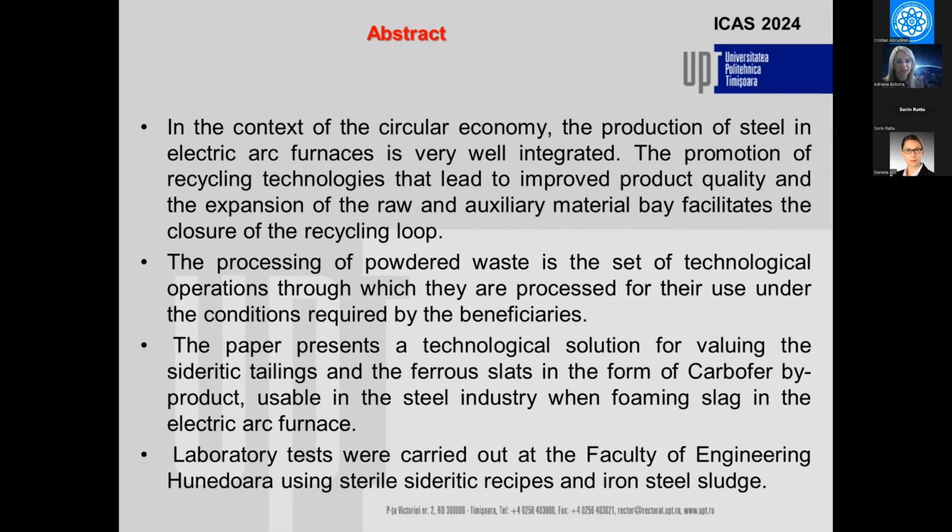The paper presents a technological solution for valorizing the sideritic tailings and the ferroslurry in the form of carbofer byproduct usable in the steel industry when foaming slag in the electric arc furnace. Laboratory tests were carried out at the Faculty of Engineering Hunedoara using sterile sideritic recipes and iron steel sludge.